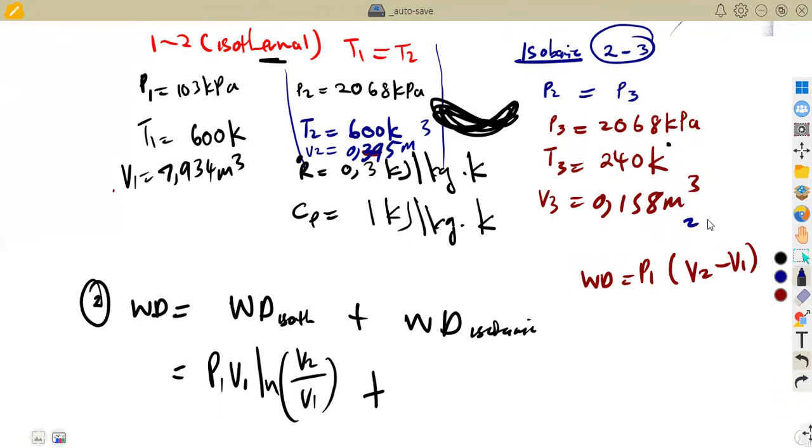So we are no longer using 1 and 2 as before. Where there is a 2 here, we're going to put it here. So this will be P2, and this will be V3 minus V2, because of the stage we are talking about. So the work done, using the correct formula and correct letters, is going to be P2, that is the pressure, into V3 minus V2.